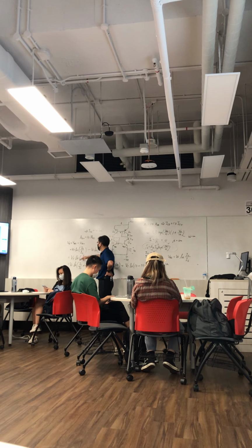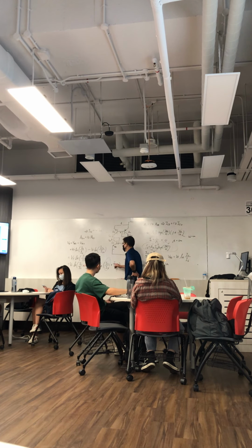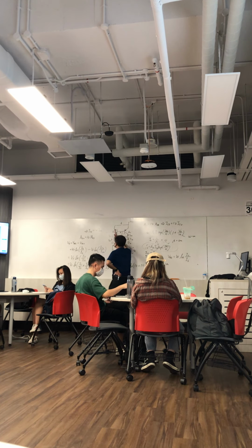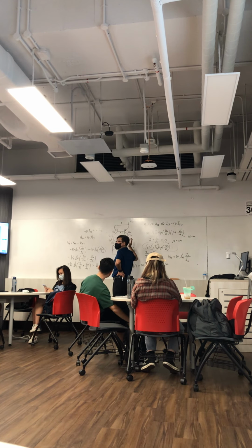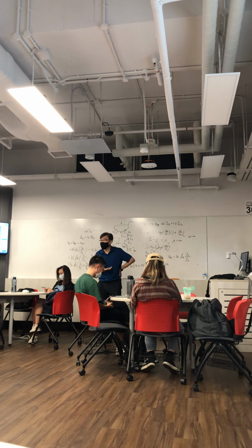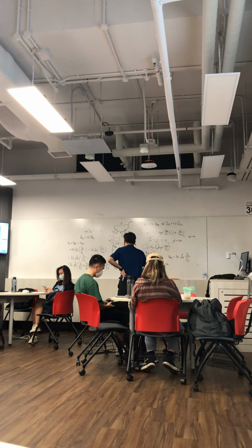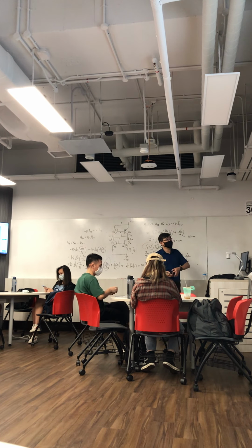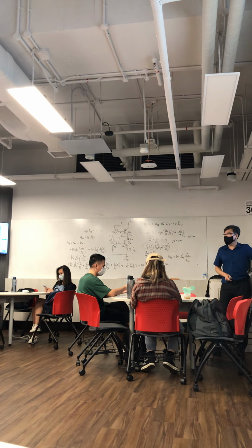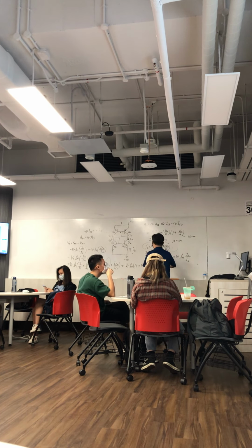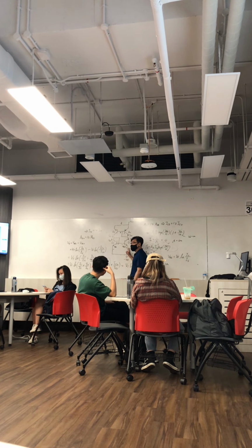Okay, once you get that, you simplify, then you know the current ratio of these two, and you also know the IS ratio of these two because it's given by the emitter ratio. So then you're able to work out the voltage across this resistor. Once you know the voltage across this resistor, you can find the current through it: take this voltage divided by this resistor.